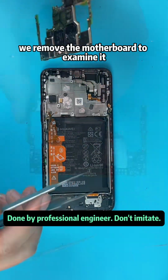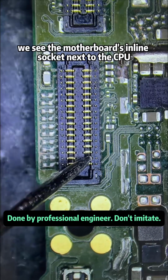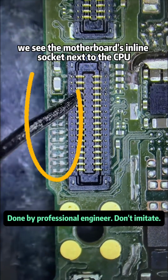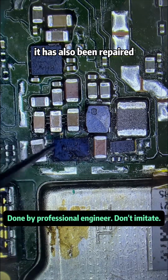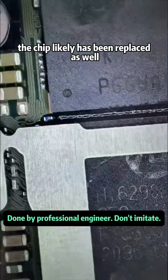We'll remove the motherboard to examine it. Under the microscope, we see the motherboard's inline socket next to the CPU is fully shorted on the MIPI bus. Looking at the display section, it has also been repaired. The chip likely has been replaced as well.